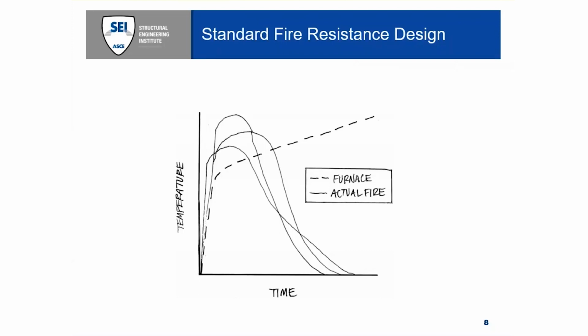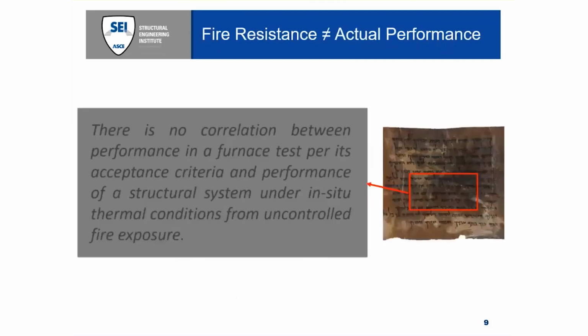So furnace test exposure does not actually represent the fire dynamics of an actual fire. Before we jump into the technical aspects of structural fire engineering, it's very, very important that we understand this. This is absolutely fundamental. There is no correlation between performance in a furnace test that qualifies fire resistance per its acceptance criteria and performance of a structural system under in situ thermal conditions from uncontrolled fire.